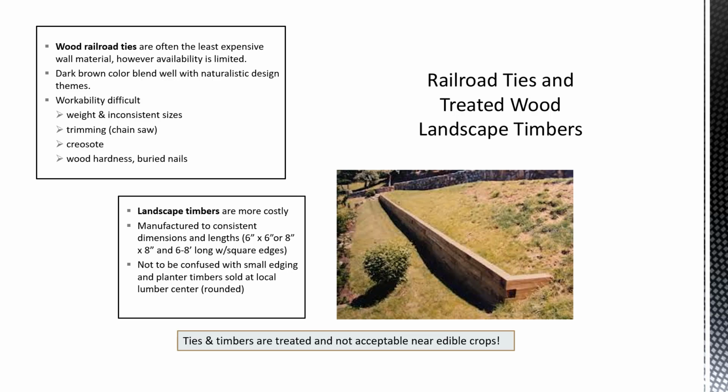And you have to do the dead men, where the wall ends. You're running those dead men back into the embankment and just down through the middle. You can probably see some of the ends of the walls where they are used as dead men going back into the embankment. It can be a little hard if you're going to try to plant trees on top of that wall. But anyway, you have to have the dead men when you're using the landscape timbers.